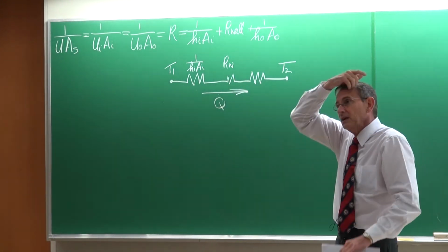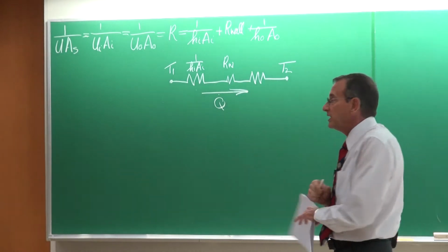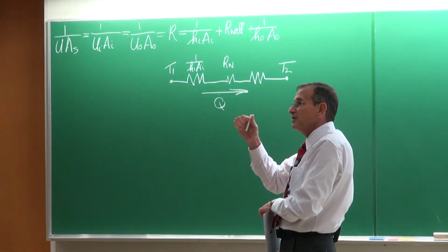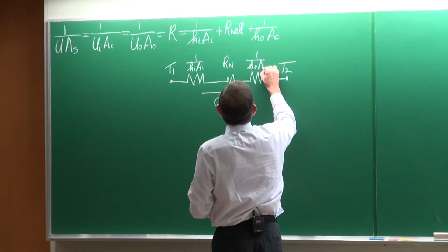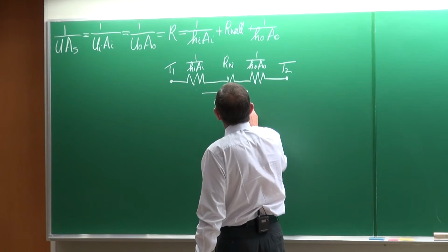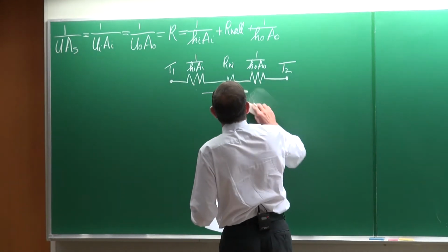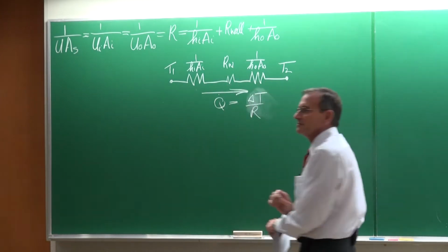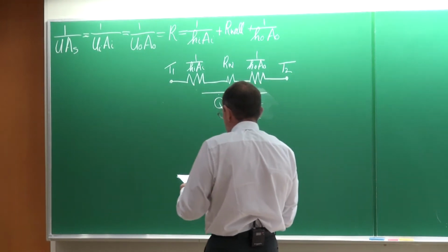If it's a plain wall, then it is equal to something like T divided by KA, where T is the thickness. Otherwise, where it is a cylindrical type of geometry, it's the ln of the diameter ratios divided by 2 pi KL, and this resistance term is equal to 1 divided by the heat transfer coefficient and the surface area. And this overall heat transfer coefficient can then be written as the resistance, delta T divided by the resistance, something like that. Okay, do you remember that? Okay, so with the previous lecture we've addressed that.